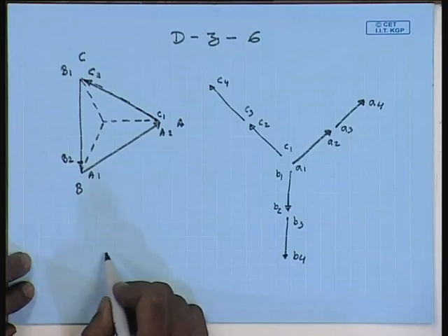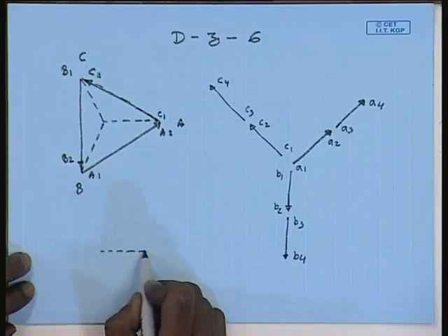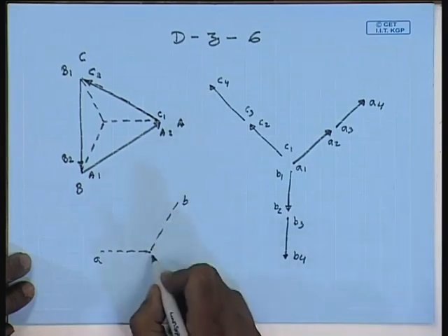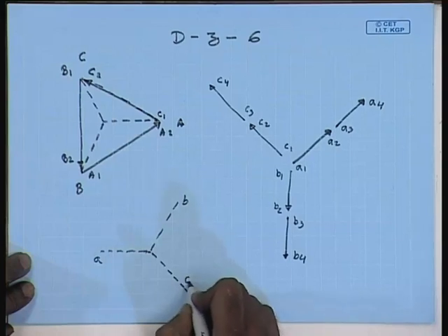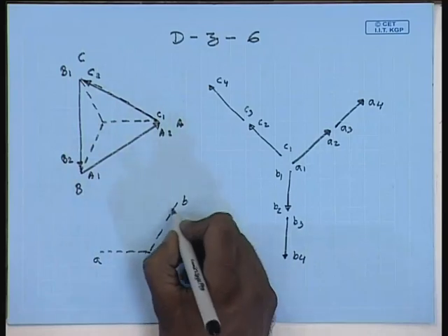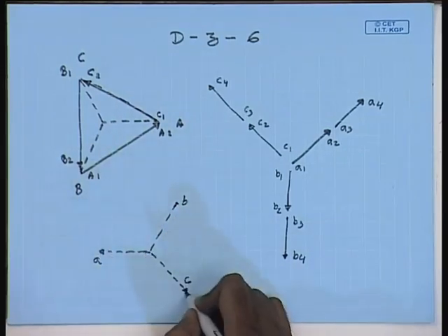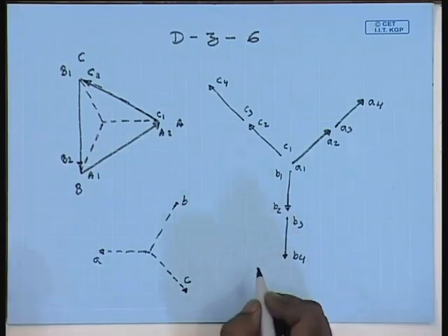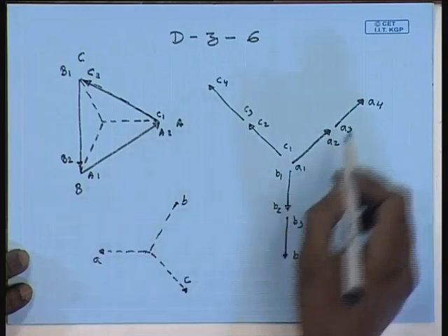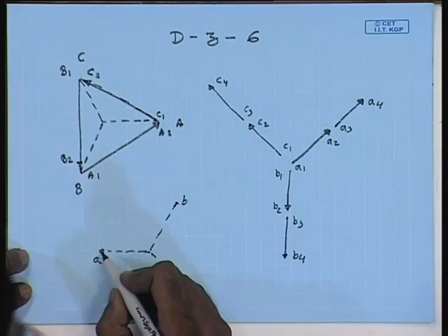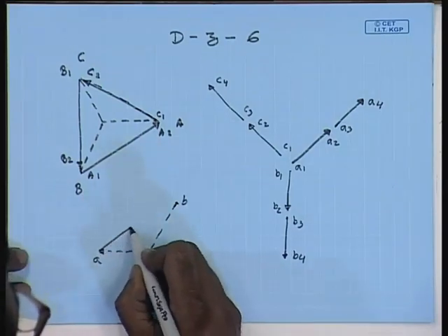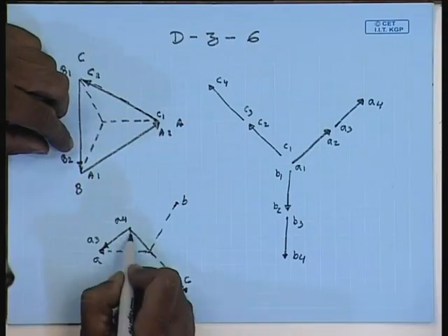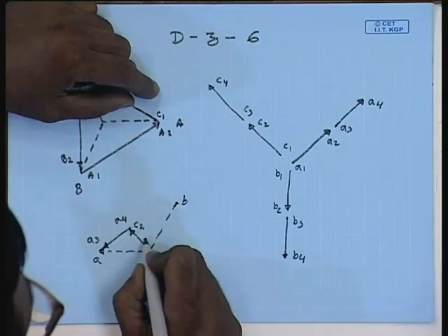So, the line to neutral voltage phasor on the low voltage side will be, this will be A, this will be B, and this will be C. So, the last leg should be formed with a voltage phasor of A, and it should point towards this. So, this is formed by taking A3, A4. Then the next voltage phasor should be this. Obviously, this should be C2, C1.